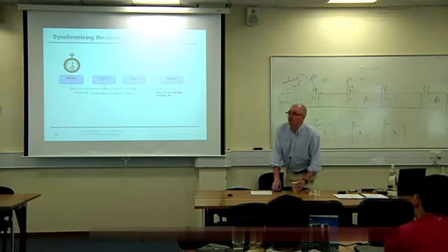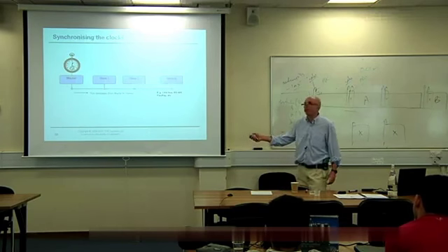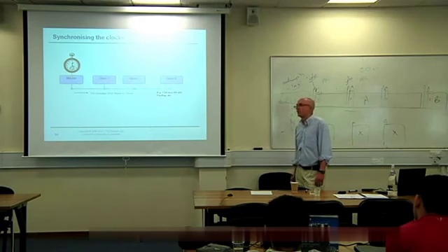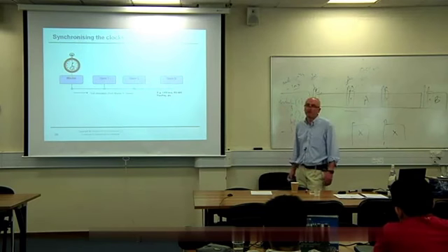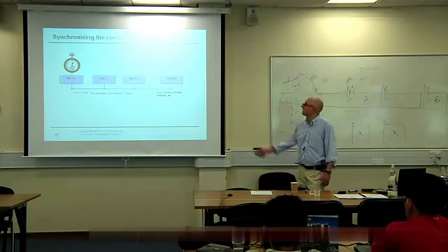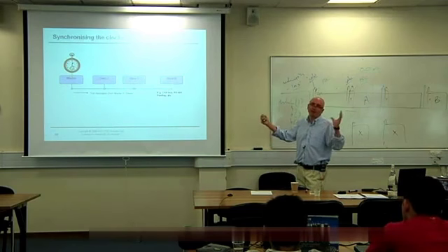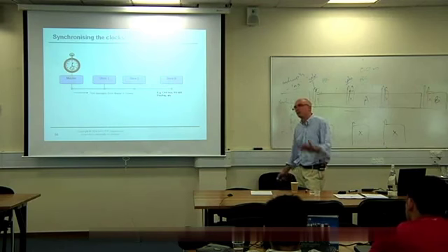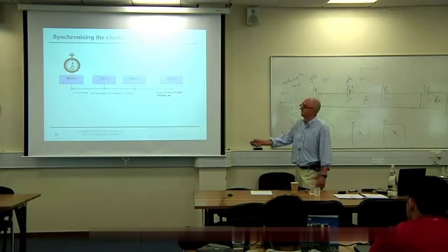So every time we get a tick on here, we set the watchdog to 11 milliseconds, say. Every time we get a tick, we refresh the watchdog. So provided the ticks keep coming, everything's fine. If we miss a tick because something's gone wrong with the bus, this will pick it up within 1 millisecond, or however fine resolution you want to set it. So the watchdog overflows after 11 milliseconds. So within 1 millisecond of the expected time, this will know what's happened.